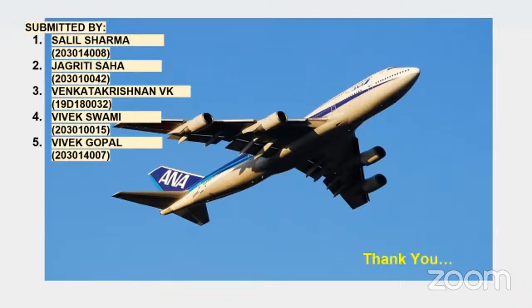So you mentioned that the maximum altitude for the anti-icing to be on should have been flight level 319, right? That is 31,900 feet. So the pilot should have known this. He should not have gone beyond 31,900 feet in altitude. Why did he allow the plane to go beyond that altitude?